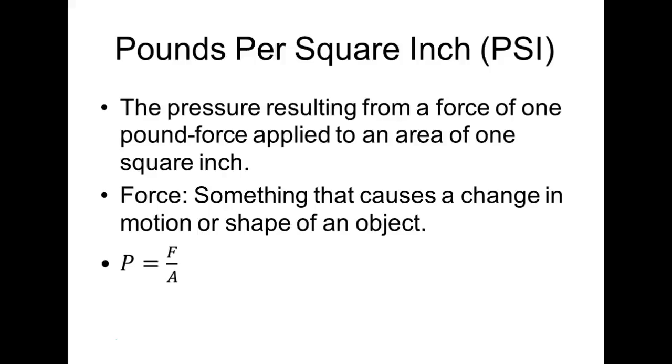Normally we use square inches. We're designating an area, right? You understand? So what's A? Area. So that is the amount of pressure that's required to generate this force. So if I redo that formula, force is equal to pressure times area. If you take pneumatics or fluid power, this is one of your main formulas.